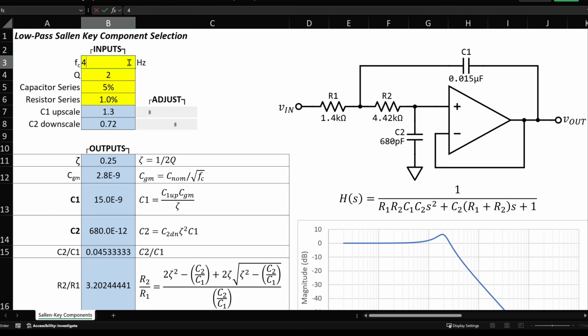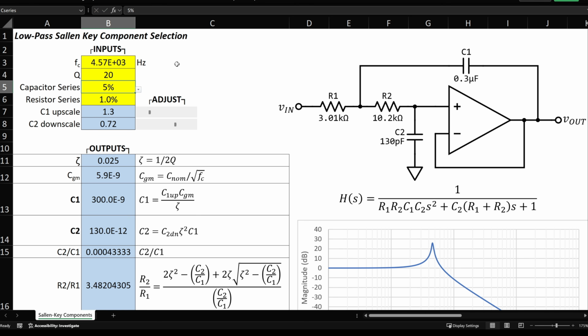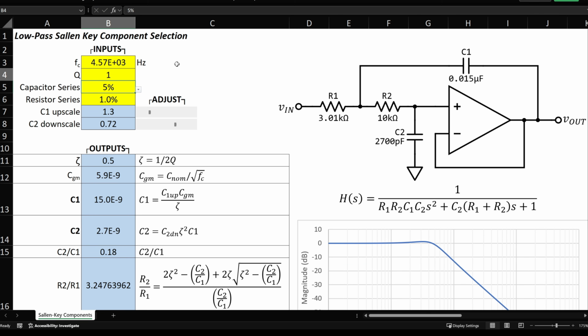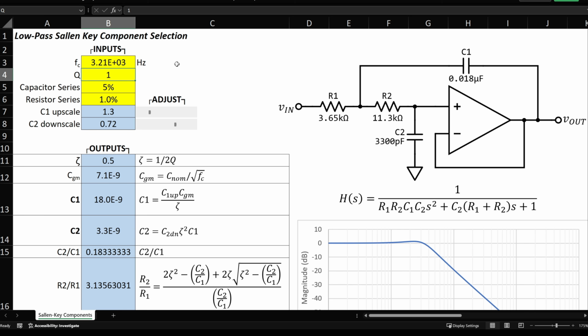I love using Excel for circuit design calculators. I draw the schematic of the circuit and have the schematic component values be dynamically linked to the calculated values. This often means the E-series function that I developed is used to return the closest standard value first.